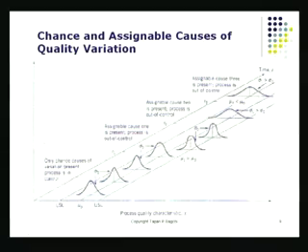It's also possible that your accuracy is fine. For example, look at this third curve here. Accuracy is fine because the average is still at mu0. But the problem is the process has become wider. It's taken over a wider distribution. This is when precision has been affected. And that would mean there is a chance, toward the tail end of this population output, that I may have some parts which are not going to be fit for subsequent use.